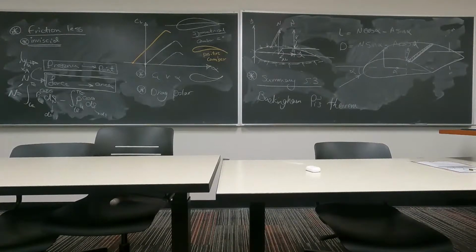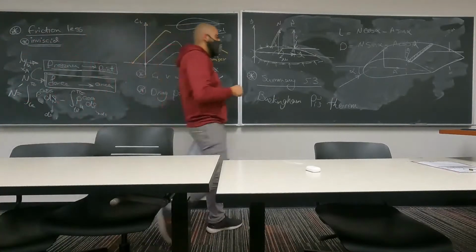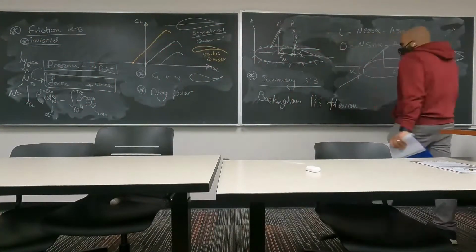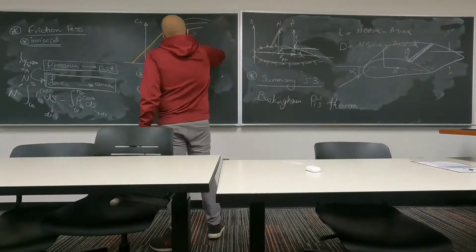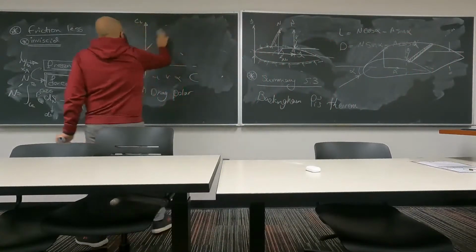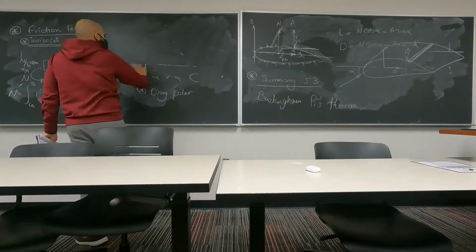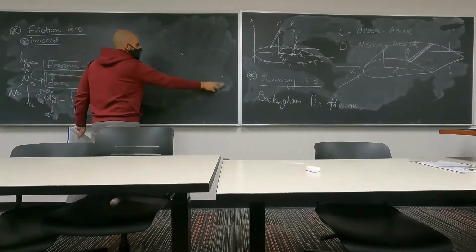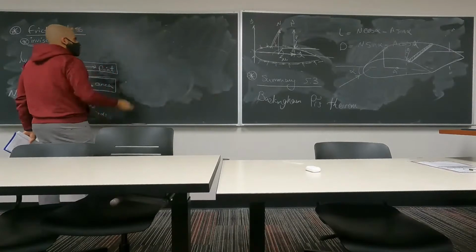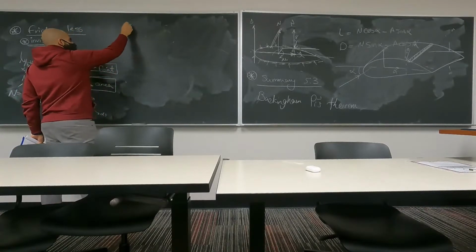Then we can use the definitions we have for force coefficients and pressure coefficient and all of those things, and relate these to your pressure. But before doing so, we're going to make some assumptions that we are dealing with thin airfoils.